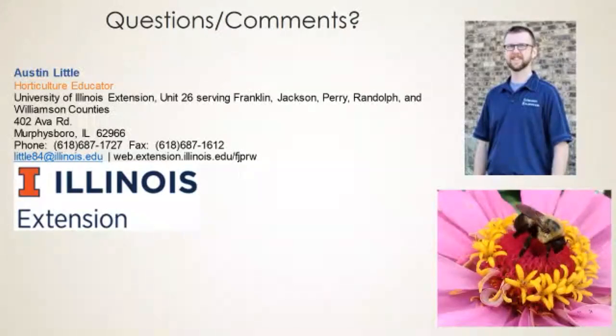So something like Nashville over the past 10 years developed these citywide policies where any new construction has to mitigate and process a certain level of stormwater from their building. And if they don't, then they pay a tax penalty, or what they say is a fee, a stormwater fee, but really it's a tax penalty.